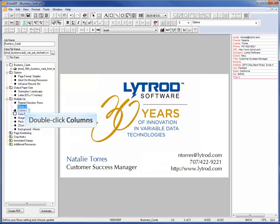Double-click on the Columns option. Type 3 and press Enter. Next, I'll define how many times I want the data to be repeated so that the same record will be used on all cards on the page. Double-click on Data Repeat. Type 12 and press Enter.